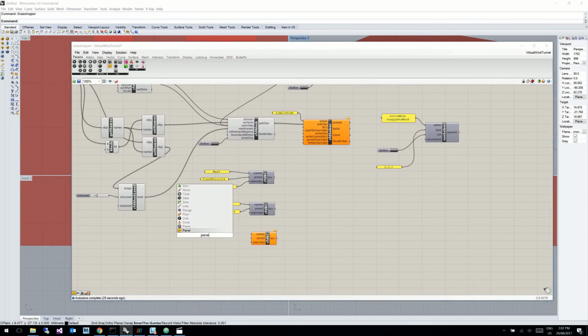So in this case, we want to set min-x, max-x, min-z, and max-z to a type of wall slip. Now it's very important that the inputs for these are multi-line data, as they're read in as a list.